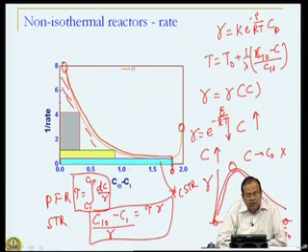So, in fact, what we have made use of in an adiabatic reactor, since temperature increases for exothermic reaction, that increase in temperature results in increasing of rates, and therefore, the residence time is smaller for CSTR. For the same reason, in a CSTR, increase in temperature will be instantaneous.